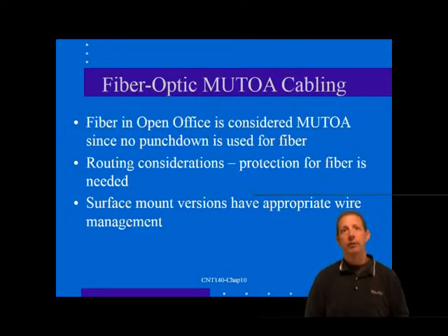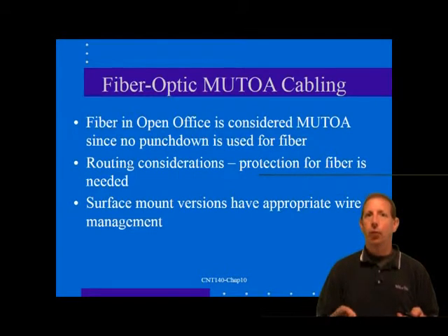In very limited modular furniture terminations, it may be possible to use some of the innovative multiple connector outlet boxes that are designed to terminate from 4 to 8 fiber pairs. These outlet boxes are designed to contain the extra lengths of unjacketed fiber strands that are required at the point of termination. They are often available in surface-mount versions that are easy to place above the ceiling grid on the walls surrounding the open office space. The availability of small form factor connectors for fiber makes this method even more practical.